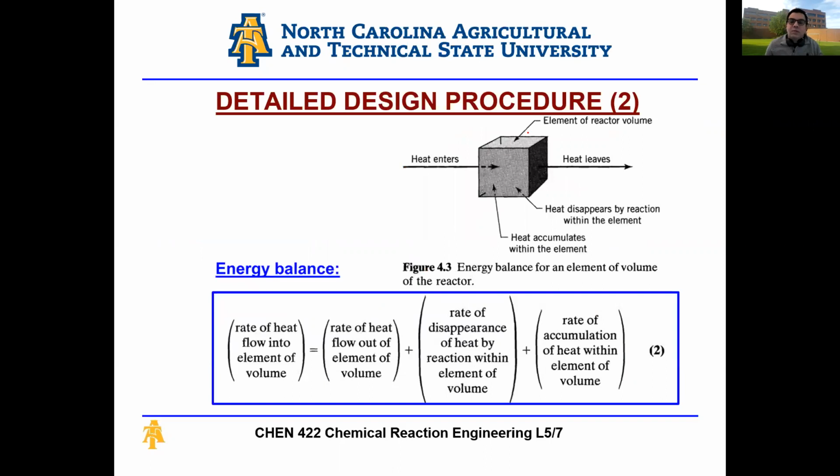Okay. Similarly, the second one is an energy balance, and you see the equation is the same. In is equal to out plus generation minus consumption, and the same idea applies. So heat enters. So if I divide my reactor into small units and I only look at a small element, and when I say I divide my reactor, so let's say you have your plug flow reactor right here.